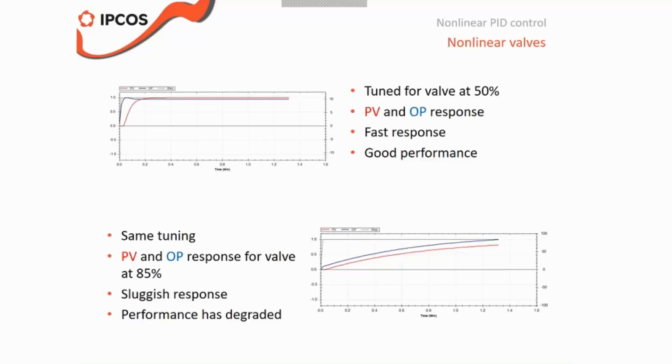The controller gain is too small here. So it's only the integral action which takes care of this. And as you might see in the plot in the top section of the slide, the proportional action is very important for this flow controller. That's the thing that's actually very low for the bottom figure, and that also means that my controller is a lot more sluggish.